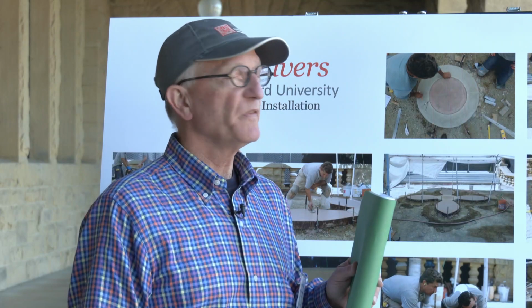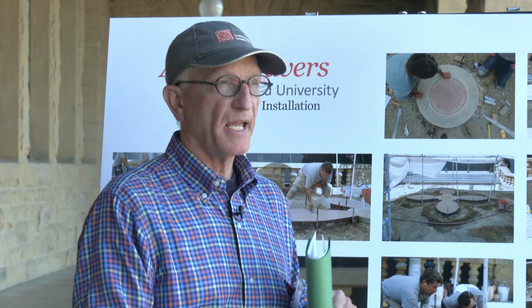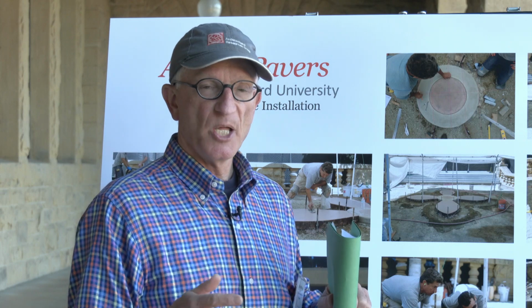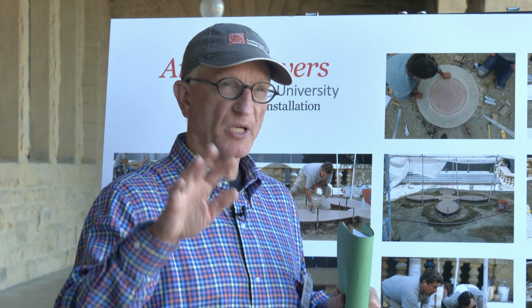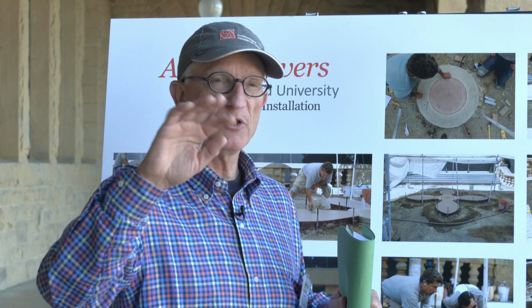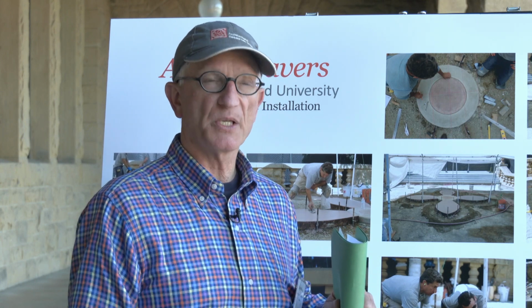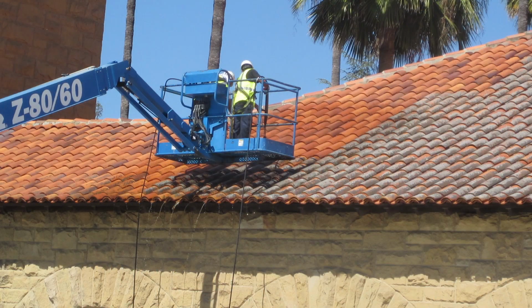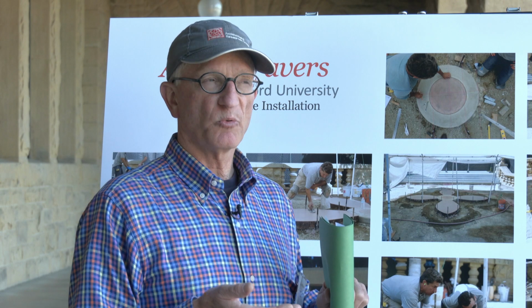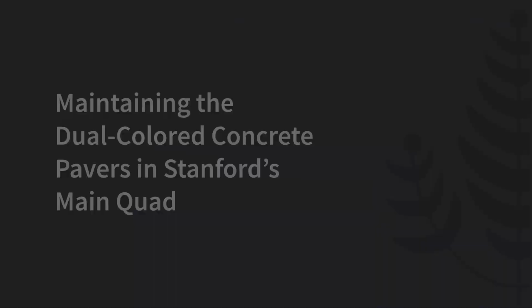Well, sometimes we've had to clean, and we want to be careful with the cleaning because we don't want to push any harsh chemicals up to reach the membrane underneath that could cause deterioration. So we like to stay with a hot water rinse, and that's basically how the tiles are cleaned. It's power washing, but at a low pressure, right? Because we really don't want to force too much water up under the roof.